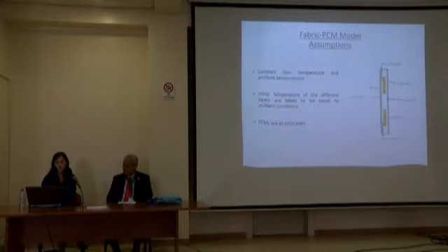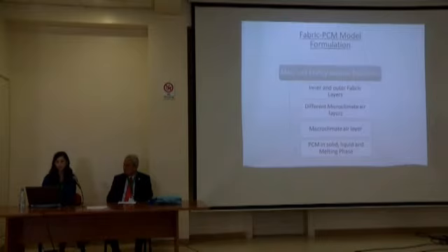Now, throughout the simulation, the skin temperature will be at a constant value. Also, the ambient temperature will be constant. And initially, the temperature of the different air layers will be equal to the ambient conditions. Also, the PCMs are supposed to be at a solid state at first. So, the mass and energy balance equations will be written for the fabric layers, for the macroclimate air, and for each microclimate air region. And finally, of course, the equations will be written for the PCM in the solid, liquid, and melting phase.